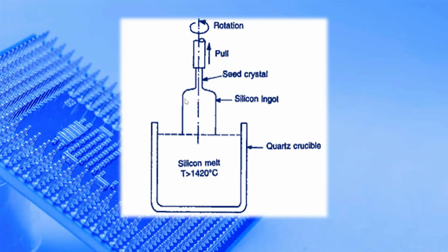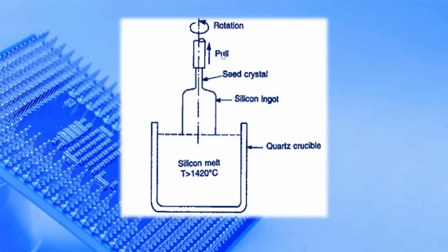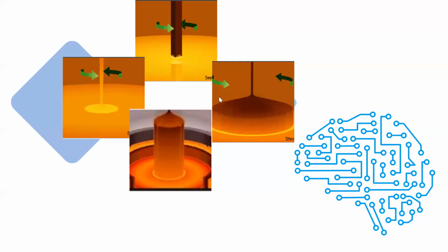The seed which initiated the crystal growth is separated from the circular ingot. The top and bottom ends are also cut off. As silicon is a hard and brittle material, industrial grade diamond is used for shaping and cutting it. This process is called ingot trimming. After completing ingot trimming and grinding, the ingot is ready for the next process, that is ingot slicing.